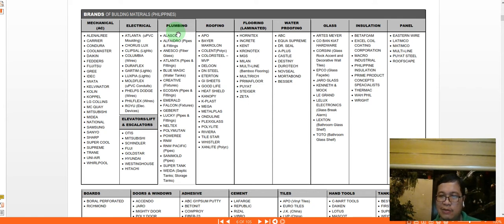To be a good specification writer, you must also be familiar with the different methodologies and how to do your pipes. Right now there are different technologies available which are leak proof. For example, you have fusion welding, wherein the pipes are welded to make sure that the joints do not leak. That's something that you can specify for your project. And for the roofing, you can also specify different roofing materials, and you can also specify something generic as long as it fits your final outlook on the design.